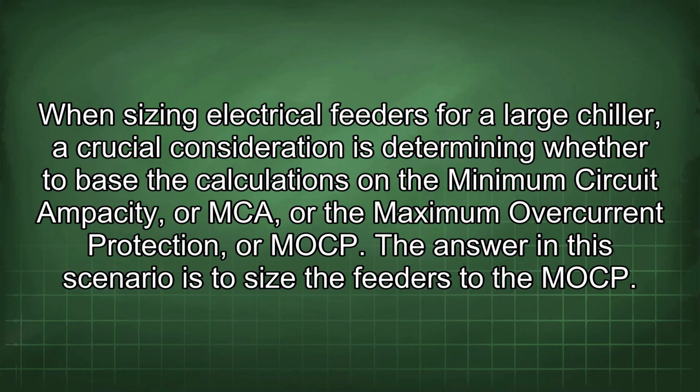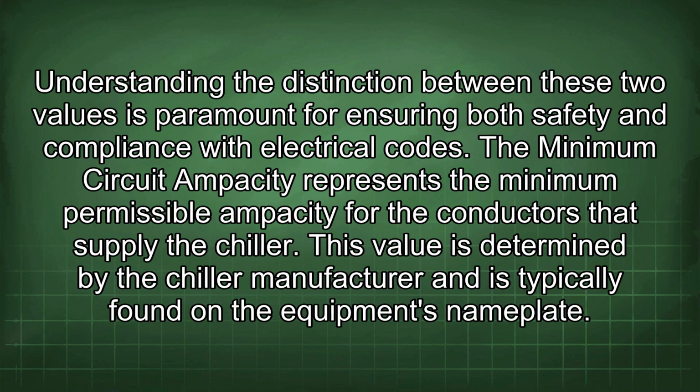When sizing electrical feeders for a large chiller, a crucial consideration is determining whether to base the calculations on the minimum circuit ampacity, or MCA, or the maximum overcurrent protection, or MOCP. The answer in this scenario is to size the feeders to the MOCP. Understanding the distinction between these two values is paramount for ensuring both safety and compliance with electrical codes.